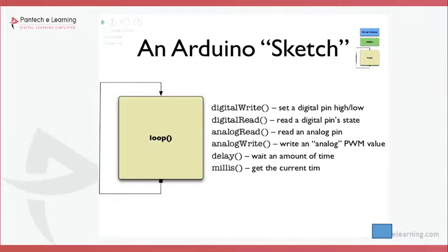These are some of the loop functions, used for repeating purposes. Digital write and read: read is for collecting or receiving data, so digital read means taking signal input, we are reading the data. Write means output, working purpose, so we use the write function. Delay uses milliseconds, how much time it will wait, we use it for waiting an amount of time.